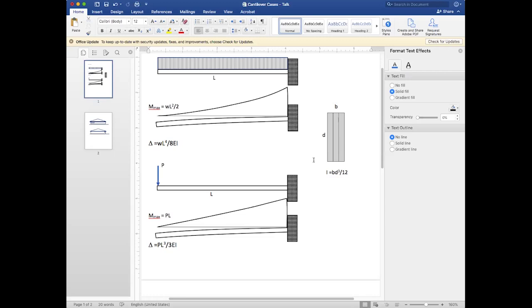So another concern with the case that I was at was to make sure that the construction team actually knew how to move them around. So the first thing in order there is you have to put it on edge to move it. Otherwise, you snap it. So those are issues with the new engineered lumbers, that the lengths can be much greater than sawn lumber.